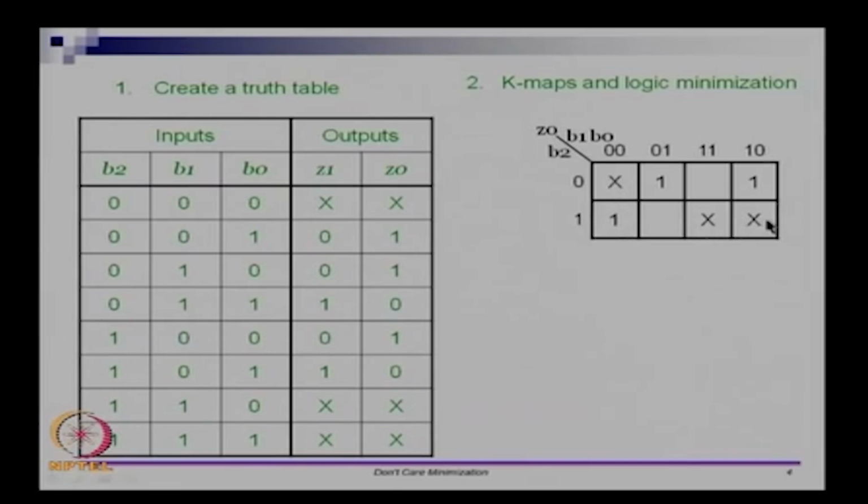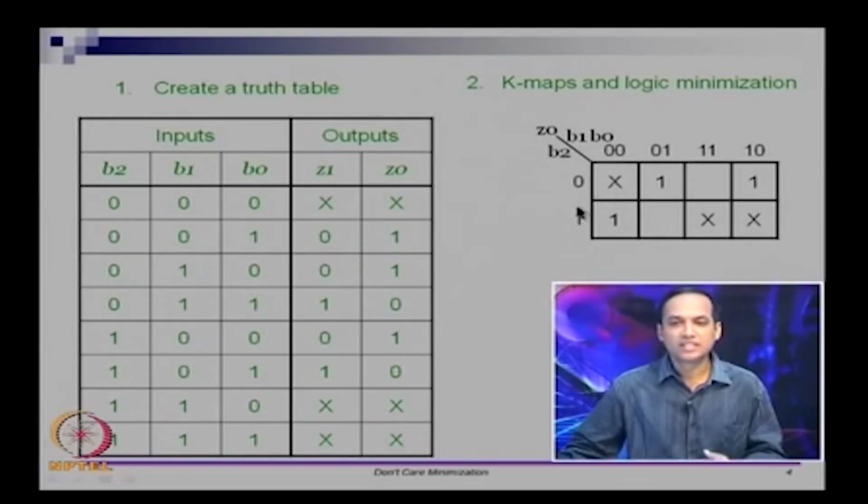Remember, it is a don't care, I do not really care about the output if some other min-term like 0, 6 or 7 comes through. So I can as well treat them as 1s. If it is a junk input, you get garbage in and garbage out. So in this circuit I am supposed to be taking only 1 to 5. If you feed 0 to this, then the output is not something that you can expect to be correct. So now I can treat these x's as 1s.